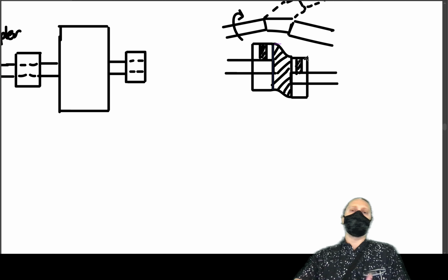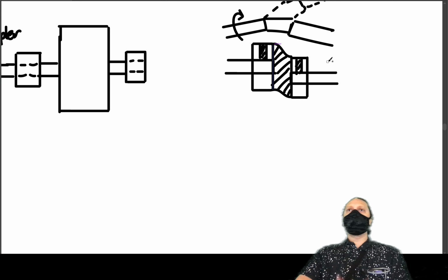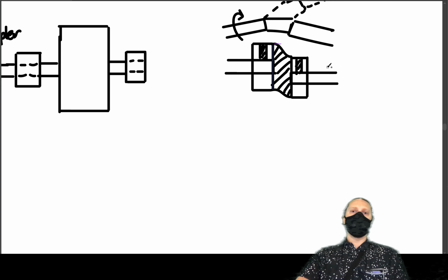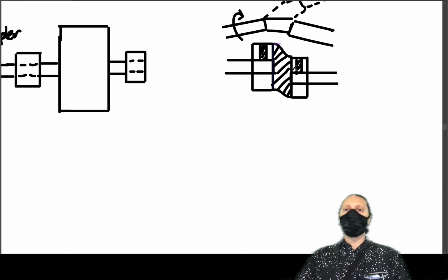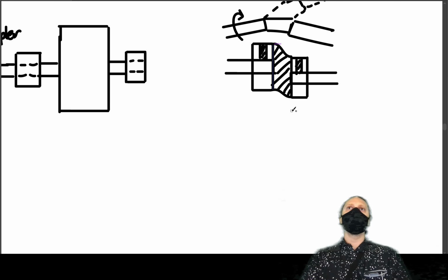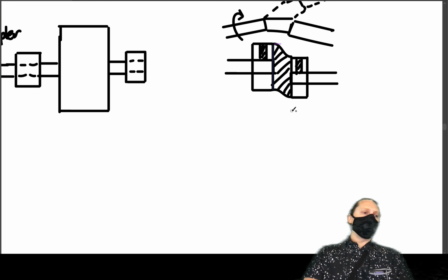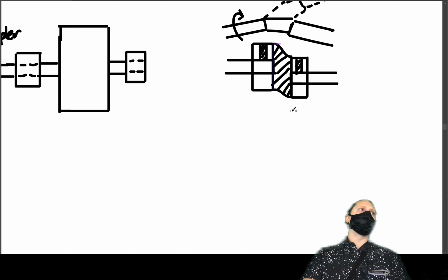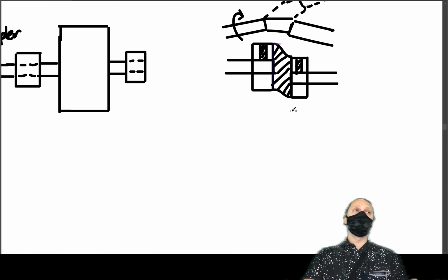There is some spring action, and the more misalignment you have, even with a flexible shaft coupling, the quicker your bearings will wear out, but at least it won't bind up and you won't have catastrophic failures. This coupler wears out too, depending on the material you use. Cheaper ones are made of aluminum. More expensive ones are made of steel. You will learn about fatigue in your machine design class, but fatigue is a big deal with aluminum. Not as big of a deal with steel, as long as you don't overstress it.